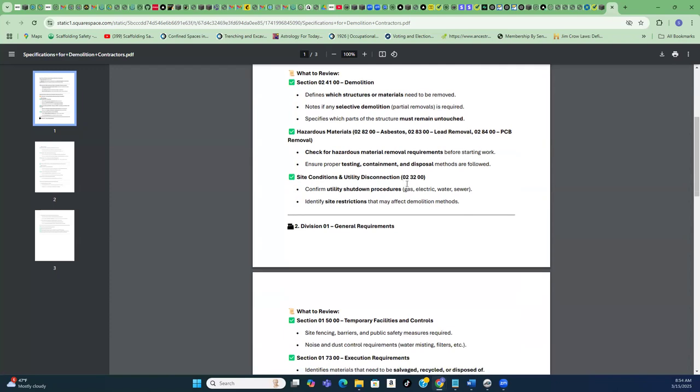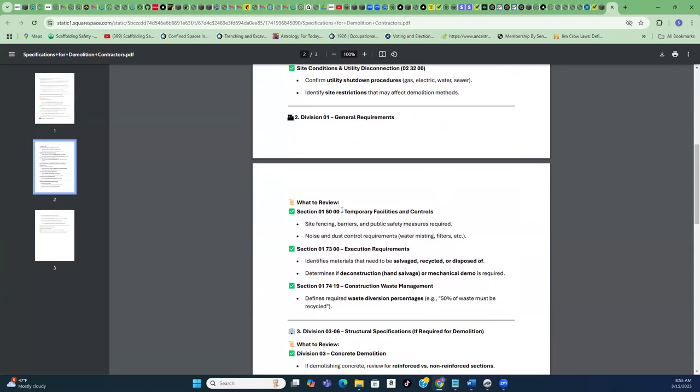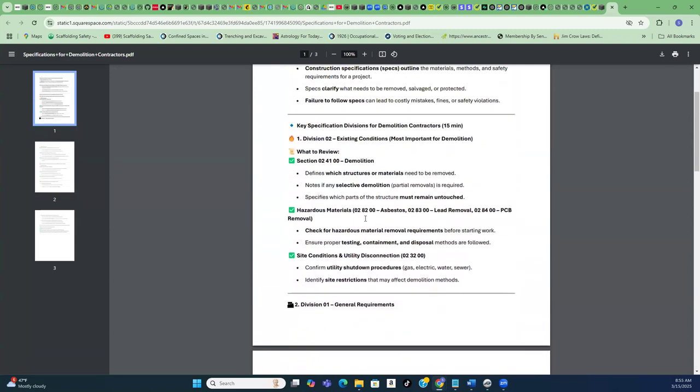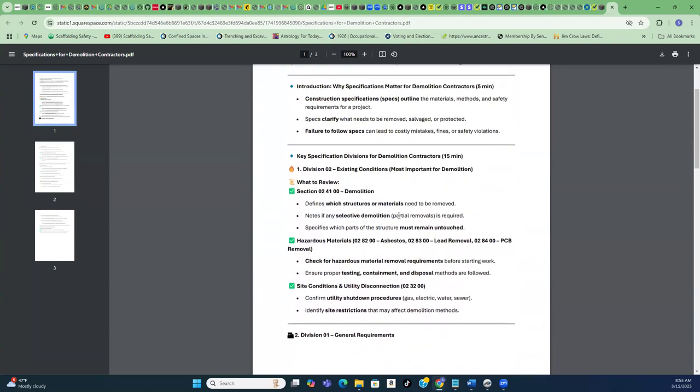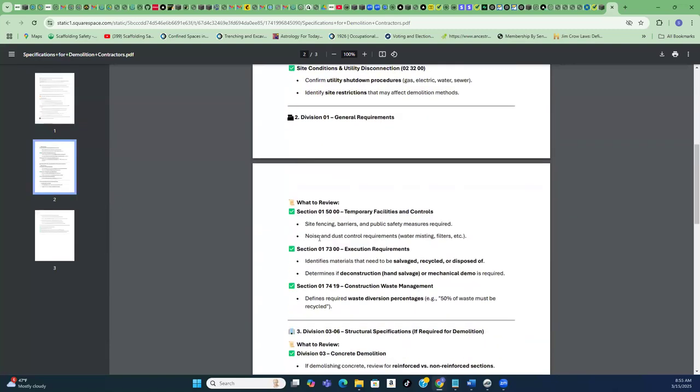Okay, so just remember, Division 02. What to review in the specifications, and what else? The general requirements as well. But the main division that tells you as far as your demo job, that's Division 02. Now we're going to go back to the general requirements, Division 01, and what to review.